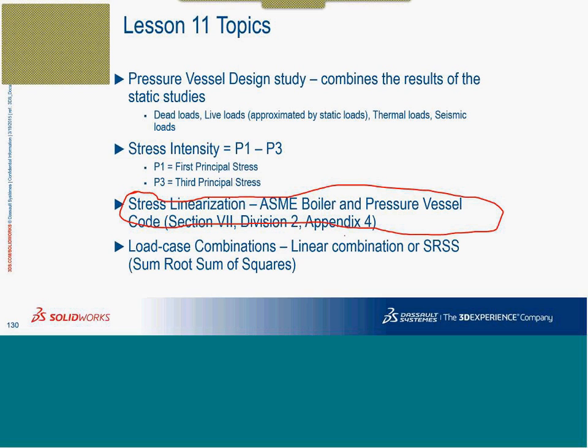Unfortunately, are we certified by ASME or anything like that? Our general purpose code is not, I would not say, a customized or concentrated code. There are other software like PVElite, etc., which have the ASME code imbibed in them, and after the analysis is done, they directly know whether this boiler is acceptable or not acceptable as per the ASME requirements.